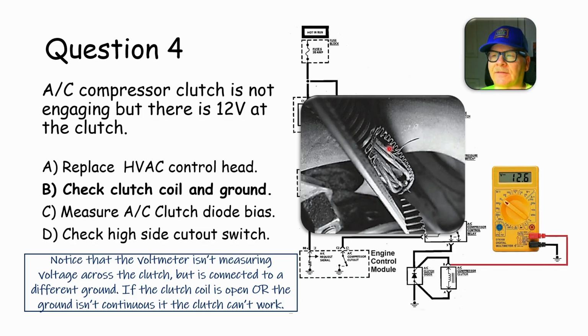The crazy thing about this Buick, it was a 93 model. Somebody had pulled all the R12 out and pumped it full of R134 and did a perfect job of it, but they didn't change the charge fittings, which was wacky as all get out. So anyway, we had to replace the charge fittings. We pulled the refrigerant out and all that nonsense with it, put it in the machine, because I had a machine that would do R12 or R134 at the time. Anyway, this one right here had a cut ground wire. We fixed the ground wire and we tied this harness back so that it couldn't get against the belt again. And that was one that we saw in the shop.